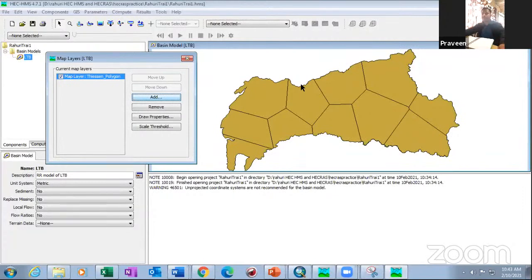That's why there is a condition for that. For a certain area, you might already know how much minimum rain gauge stations should be there to satisfy the requirement. That computation should be done beforehand. You might have solved this problem in your graduation: for a certain area and a given number of gauging stations, whether it is sufficient or not. Do that computation first, and then come here and start the modeling. If it is insufficient, the model will not give any error, but the results will not be meaningful.